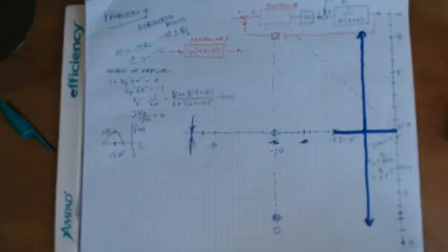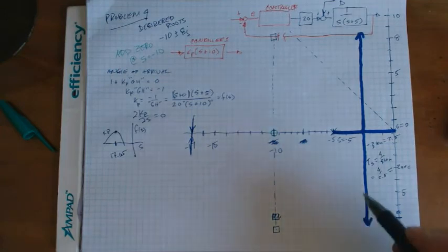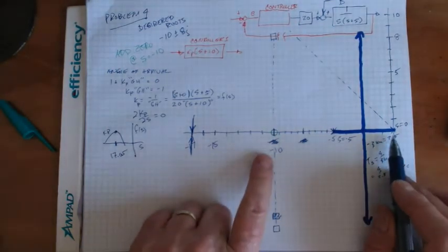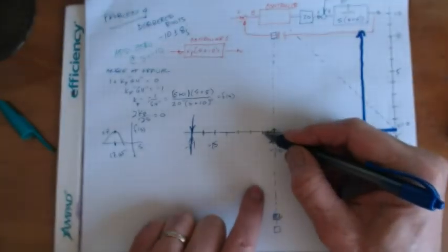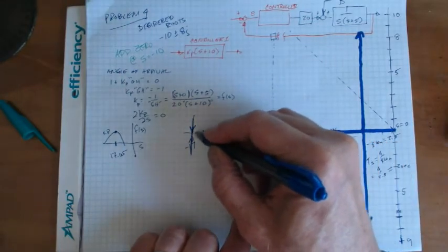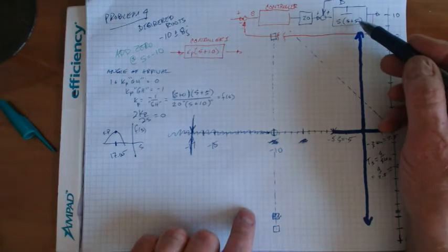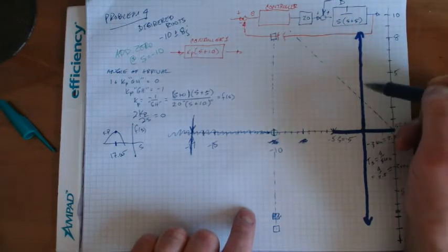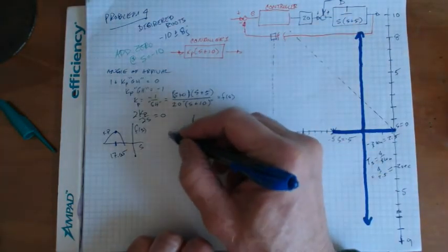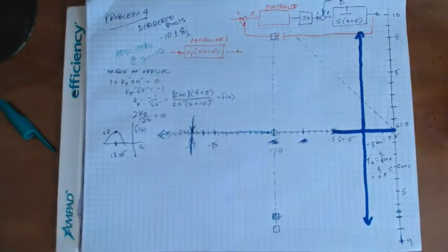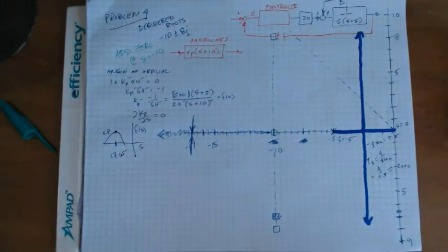So that's where the angle of arrival gets to be, right? Because one of the things that happened here is if we look at where the real axis segments are, this adds another piece of real axis segment here. What we used to have was the number of finite poles minus the number of finite zeros, which is 2. So there were 2 infinite asymptotes. When we add a 0, there's only 1 now, and it's at 180 degrees, so it looks something like that.